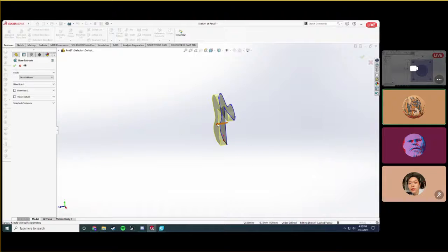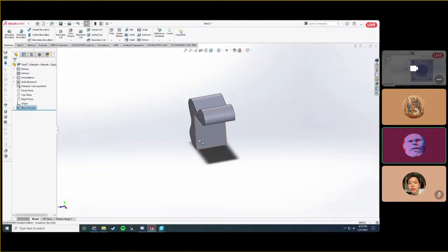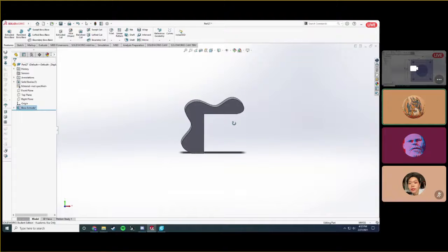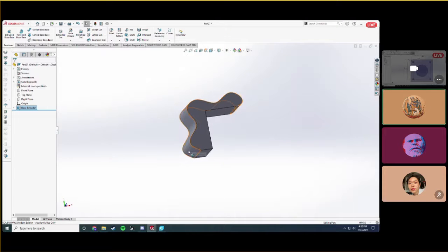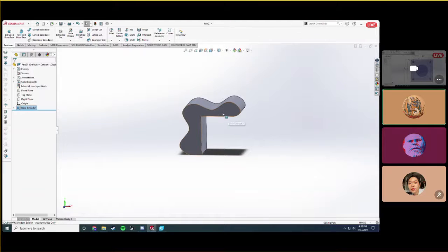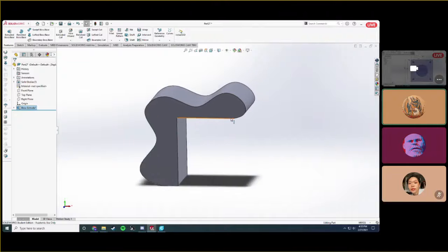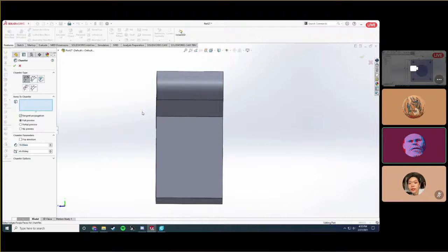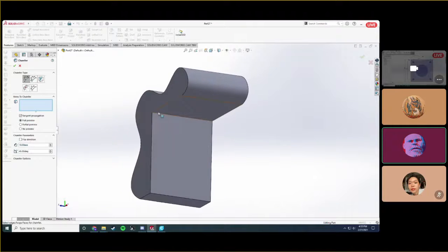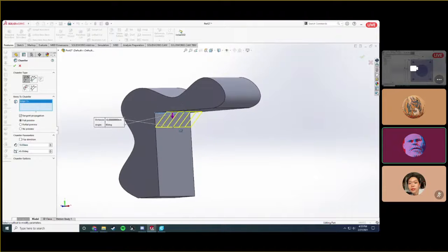Extruded this. I don't know, it really doesn't matter how much I extrude it. Let's say we have this and we want to print it. We would have to print it on this space right here. And we would still need support coming out here just for this part. But this couldn't really print. It would come out and come back and then it would just all droop down. There's nothing to support this side. So you can either add a lot of support material, like that blue stuff that you saw in the slicer, or you can design the part to not need that.